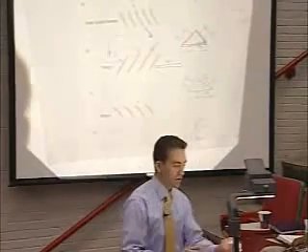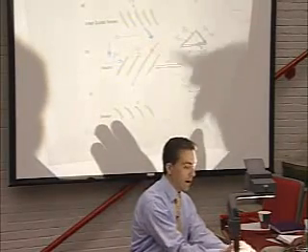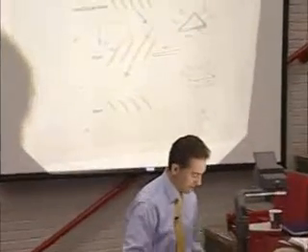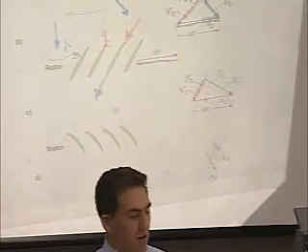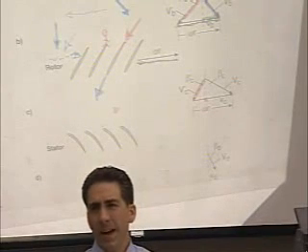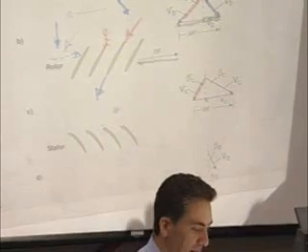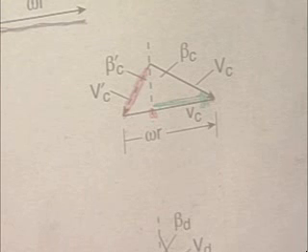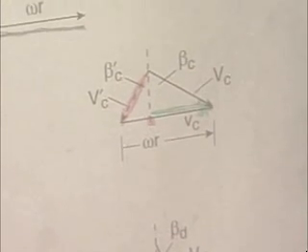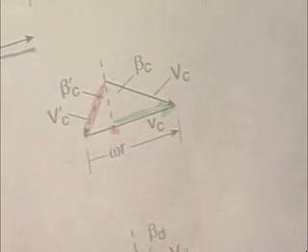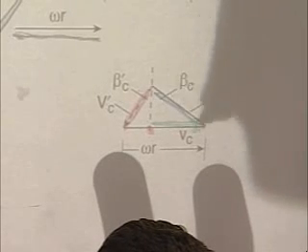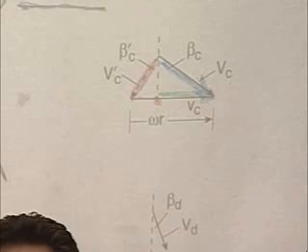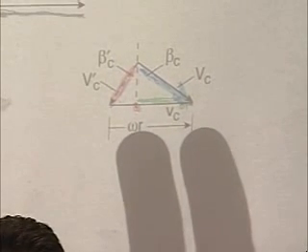In the reference frame of this blade now, you assume that it leaves at the flow angle, or at the trailing edge angle. That is this, which I keep drawing in red to stay consistent over here. So that's the flow angle leaving these blades. And now, what I really care about again is this component in the stationary frame. So how do I get back to the stationary frame? I add omega r, which is this black line on the bottom, to this red vector, and now I'm back to the stationary frame. And the component that I care about is the tangential component, which is that little green vector along the bottom.